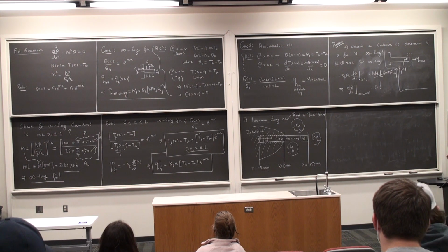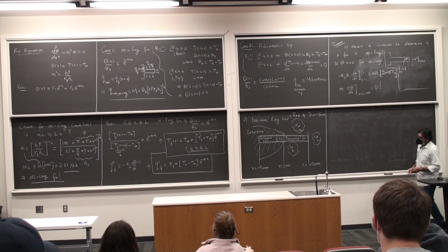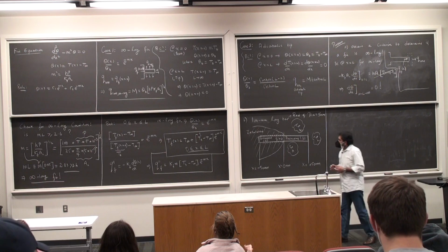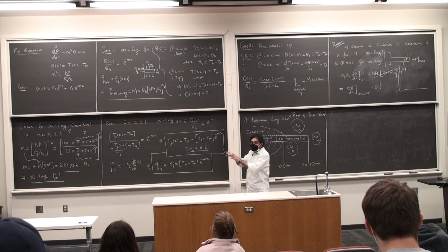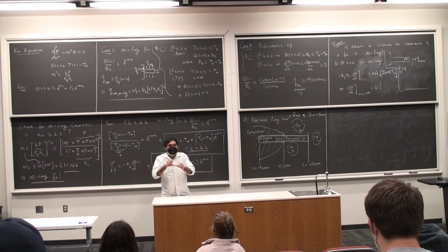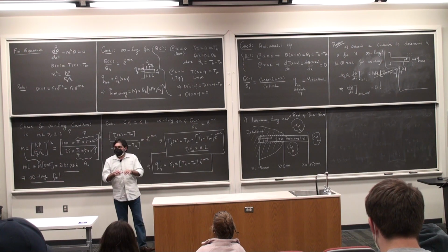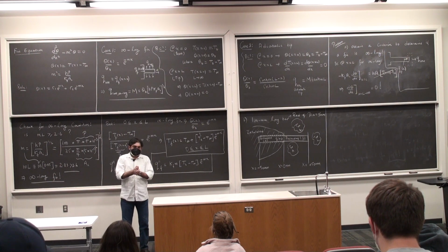I have one unknown that is to be discovered there. Hopefully boundary conditions will give us something. But then I have this portion that is embedded within the wall. So I essentially use the 1D heat diffusion equation, starting from x is equal to minus L to x is equal to 0. Because this is nothing but a plane wall. Right?